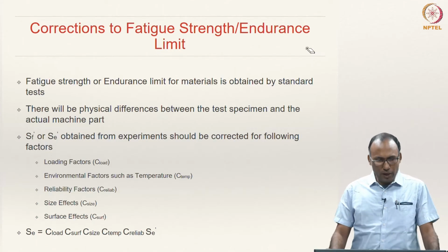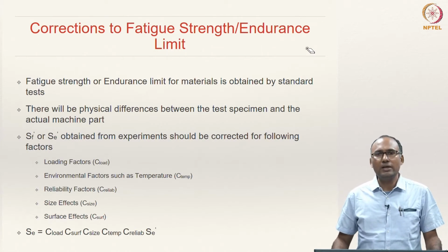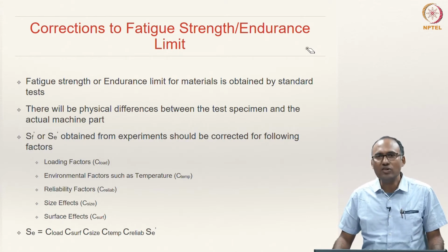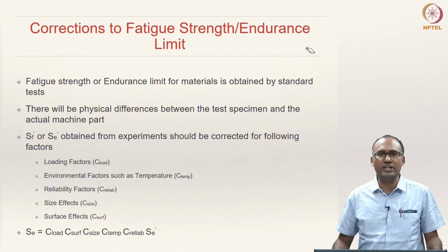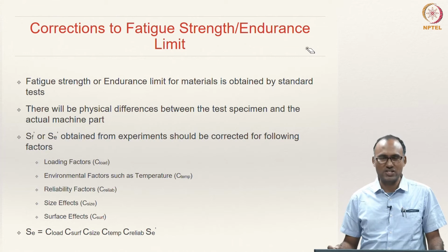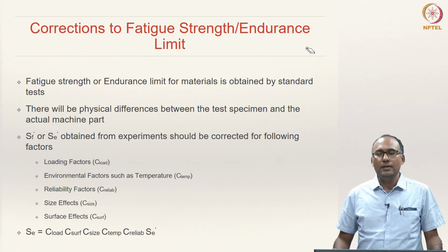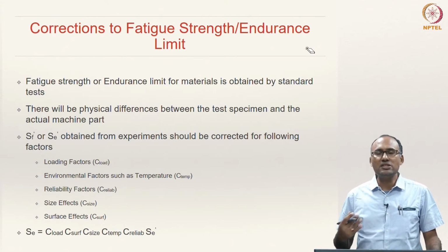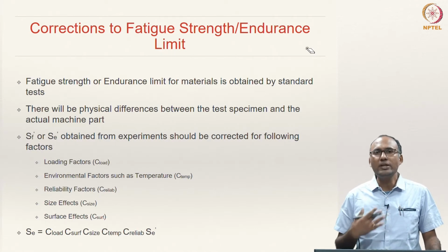So, now in the previous discussion, when we calculated the endurance strength of the material, which we always call the uncorrected endurance strength or uncorrected fatigue strength of the material, which we have designated with SE dash or SF dash. SE dash is our uncorrected endurance strength.